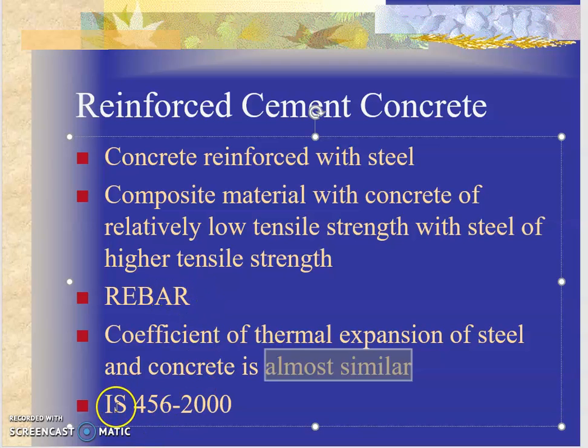Okay. Further, if you want to go into the depth of designing of RCC, there is an IS code dedicated for RCC, and that is IS 456:2000. Reinforced cement concrete is primarily used as a structural member. Why is it used as a structural member? Because it is very high in strength. You can alter its strength as per your requirement. Okay. RCC starts from M15. Anything less than M15 you cannot go for RCC.